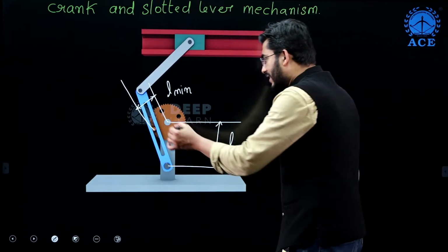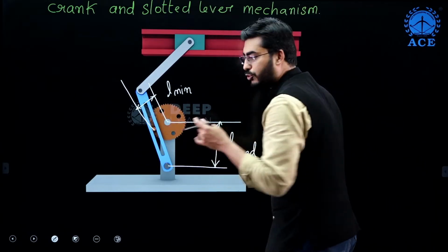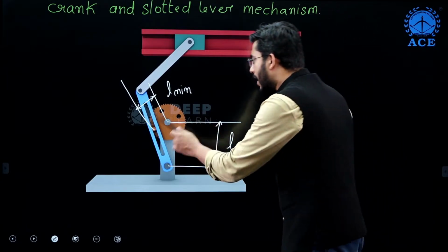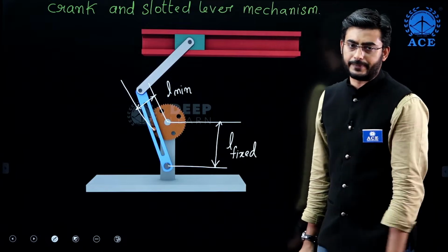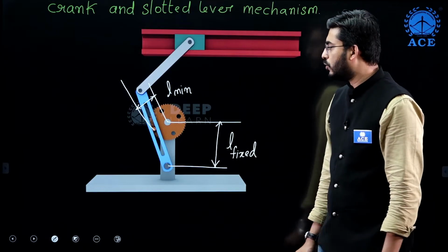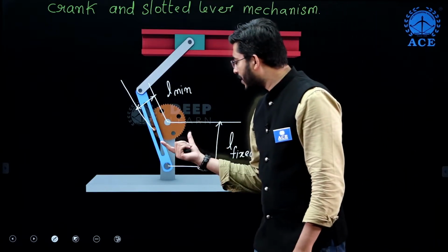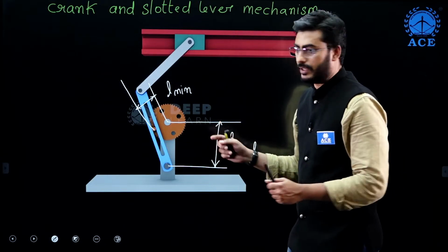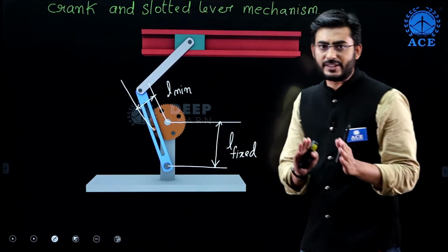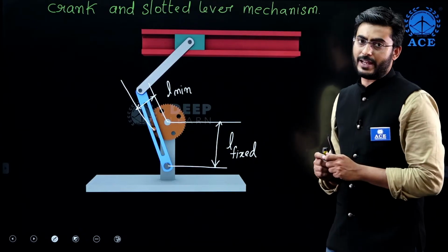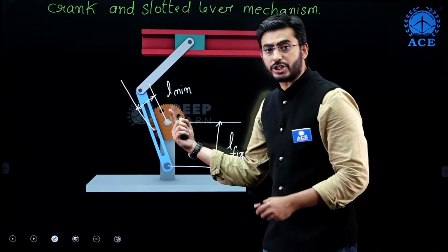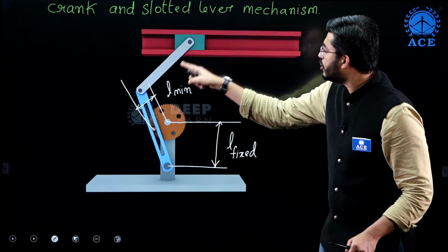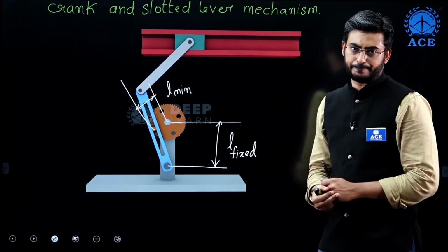We know that this toothed wheel is going to act as a crank, and the slotted bar is going to oscillate. So this is an application of the crank rocker mechanism. This is purely working on the basis of the crank rocker mechanism. The oscillatory motion of the slotted bar is transmitted through this rod to the cutting tool over here.